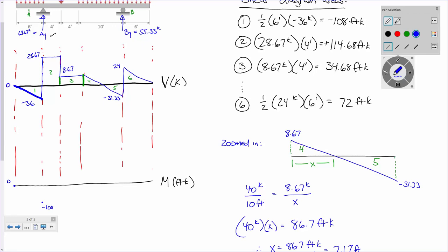So you can think about it like this. Little to a lot, little to a lot. That's all there is to it. Because it's that relationship between shear and moment. So you're basically integrating the shear diagram. Basically, that's what you're doing. That's what a moment diagram is. Moment is the integral of shear. That's what it is.